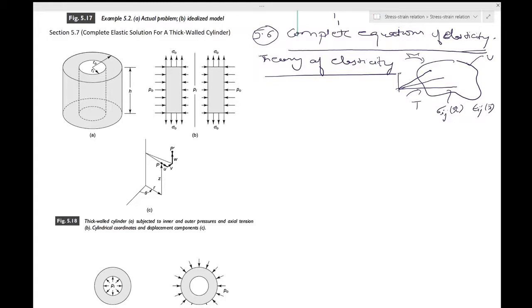Now the problem is to find the stress and strain which meet the prescribed load and displacements on the boundary, and which at every point within satisfy the equilibrium equations, the strain stress temperature relations, and the geometrical conditions associated with the definition of strain and the concept of continuous displacement. So basically everything which we have studied all this while. So that's what we will want to do.